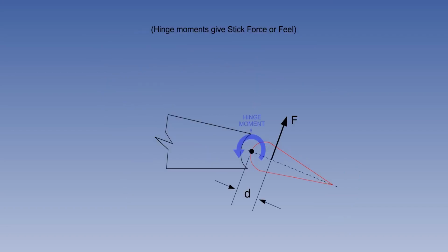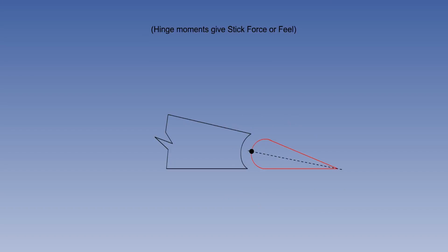The force the pilot must apply to move the control surfaces into the airflow or hold the required angle of deflection must not be too high. When the pilot moves a control surface, the airflow resists. An aerodynamic force will try to rotate the surface around the hinge in the direction in which the force is acting.